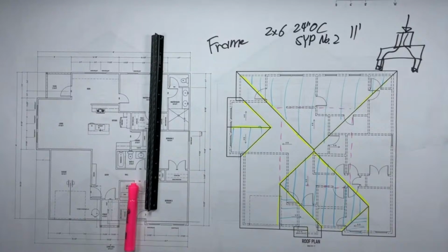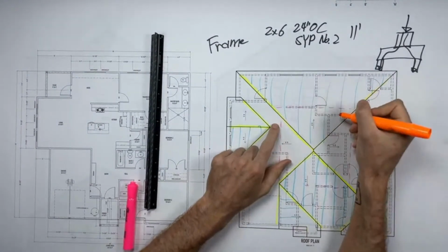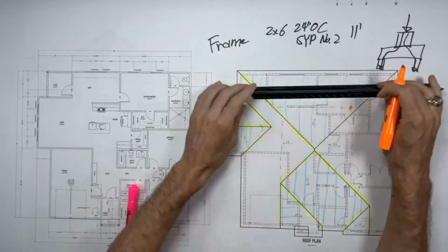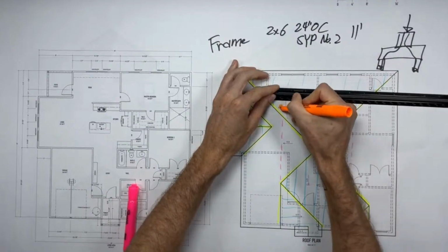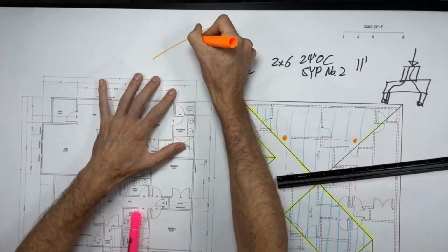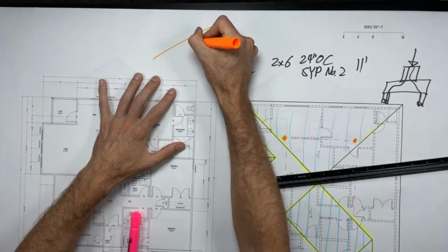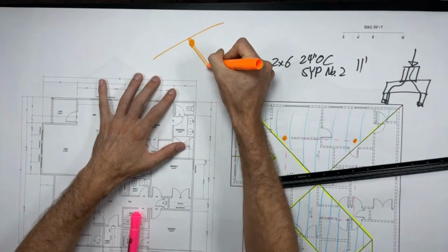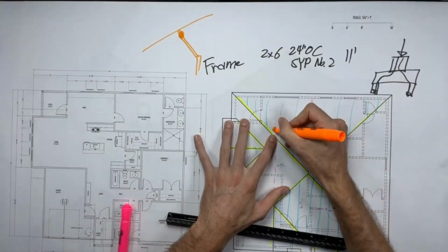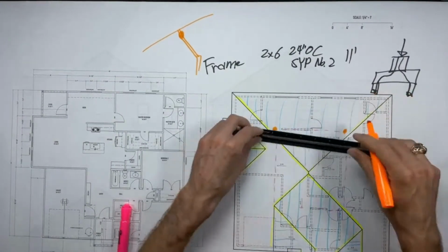And I've already got blue rafters, so how about we use orange instead? So we want to brace this about every 4 feet. I would take my scale and start on the end. I'd make a circle. The circle means, if this is my roof and I have this purlin, the circle is the brace. This is where we're connecting to the purlin going down to a wall or something, whatever's in there. That's what this circle represents. So the circle is where we connect to the roof, and we draw the brace to where we're going to put the load.